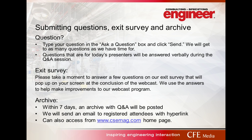So this is something that comes up a lot and is a typical confusion from what we can do in other commercial buildings using ASHRAE 62.1 versus the ventilation requirements that 170 imposes. Standard 170 is only a prescriptive-based ventilation requirement. So there is no way to use any sort of air cleaning system to allow a reduction in that. Now, there's nothing that keeps you from employing such systems. I know that there are lots of healthcare facilities that do, but it doesn't allow you to reduce the amount of ventilation required to the system in the same way that you could with a commercial facility utilizing the indoor air quality procedure of ASHRAE 62.1.